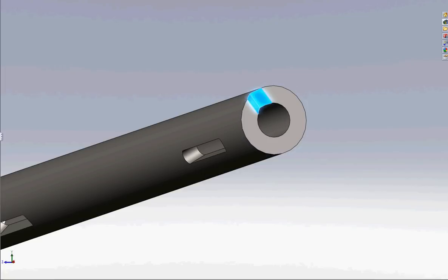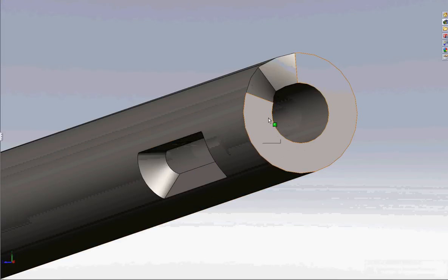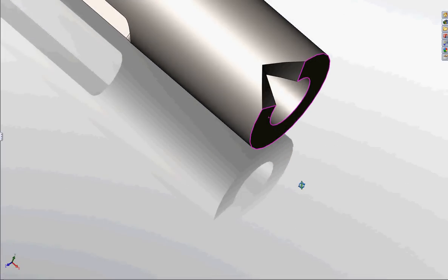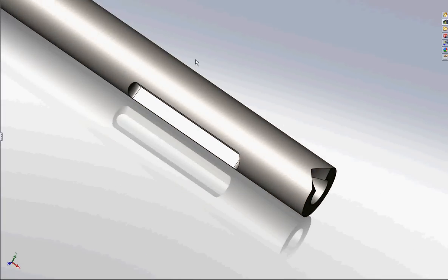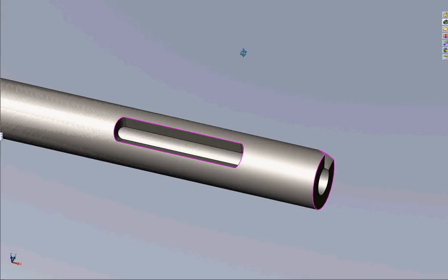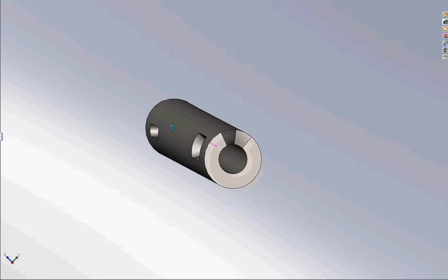Now, the problem you run into when you're doing that is that your cut actually winds up looking like this. So this is what you're really going to get coming off of a 4-axis tube laser. Now, there's places out there that have 5 and even 6-axis tube lasers that can angle the head, and they can do all kinds of things, and normalization's not as big an issue with them. However, on this particular part, it wouldn't matter because our heat is the issue. So we have to point the laser beam.